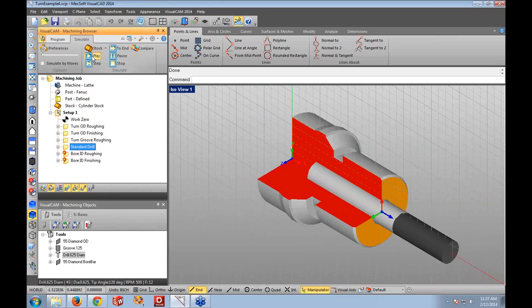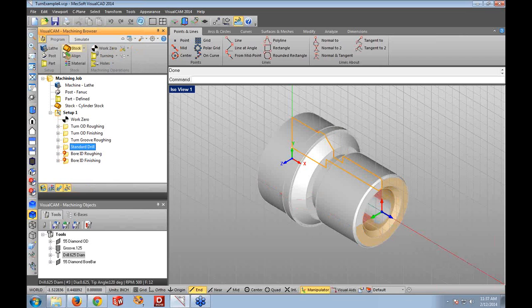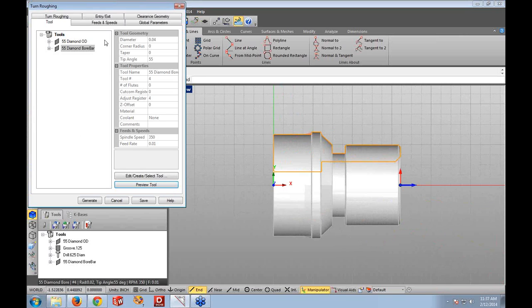The drilling operation, and then this one shows a straight shot drill right through. Could be a super drill, taking out the center there. The second operation again is just roughing, but we're specifying a different tool, an ID boring bar, in which we're going to rough out the excess material from the drill hole to within a stock value of the inside diameter. So we'll generate that.